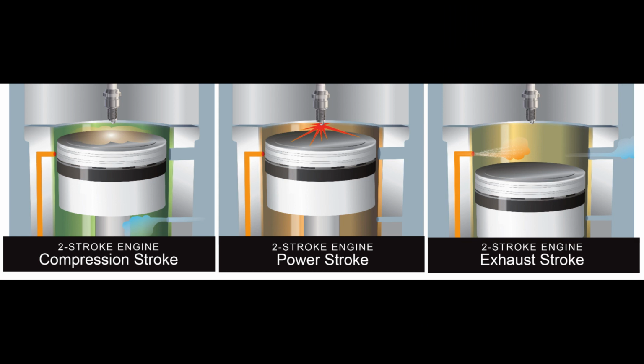Combustion. During normal combustion, the fuel/air mixture burns in a very controlled and predictable manner. Although the process occurs in a fraction of a second, the mixture actually begins to burn at the point where it is ignited by the spark plugs, then burns away from the plugs until it is consumed completely. This type of combustion causes a smooth buildup of temperature and pressure and ensures that the expanding gases deliver the maximum force to the piston at exactly the right time in the power stroke.